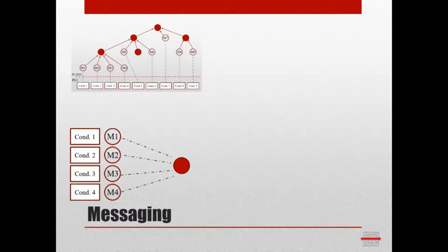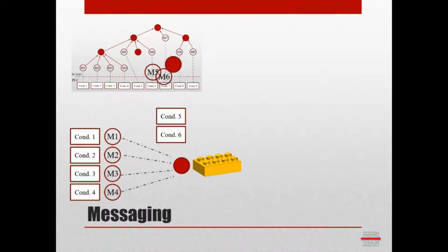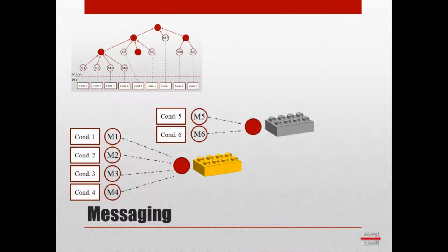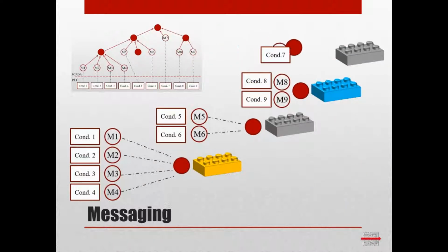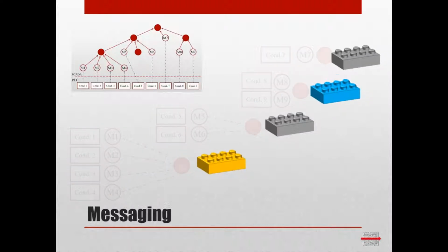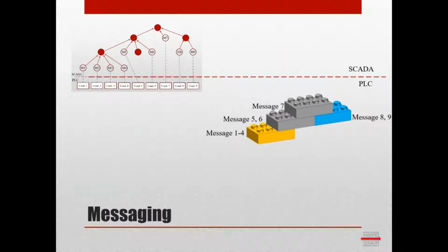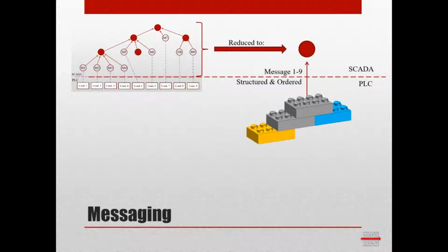In PLC-Easy, a message is associated in the PLC with the software module. So this can be associated with a control module, equipment module, a unit, a process cell. And these messages can be changed in runtime dynamically. Because the application is built according to the S88 model of the process, all messages are automatically grouped, ordered, structured, and masked according to that architecture. And the SCADA effort is now reduced to the instantiating of the object and placing it on the graphic.